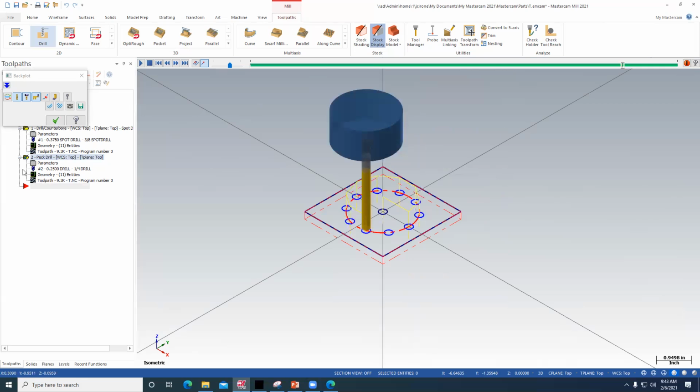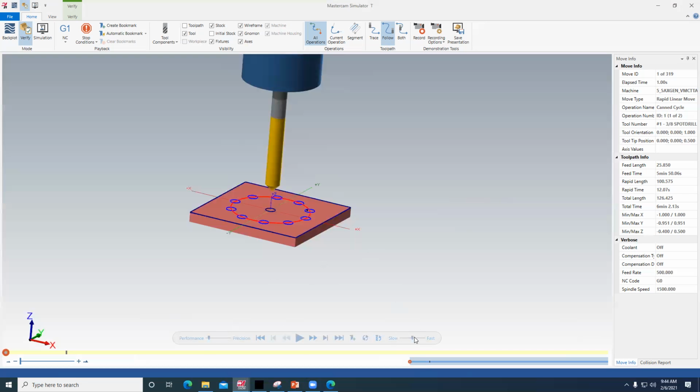And then, as we said, you can select those, go to the tool, right mouse click, select library. And this time, I'm going to say I want to drill. So I'm going to drill. And I do a search. You filter all the drills in my library, and select it. Basically, I'm going to the parameters, and I'm going to drill. So I got to back.